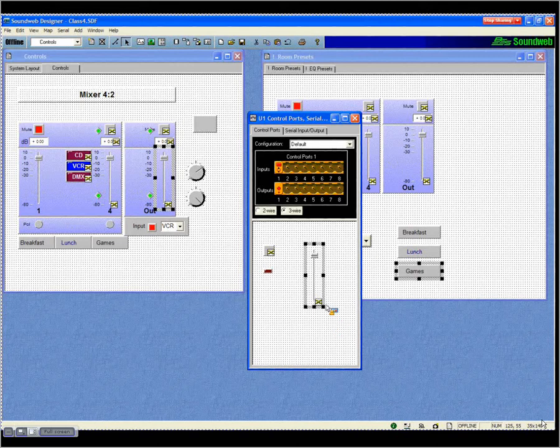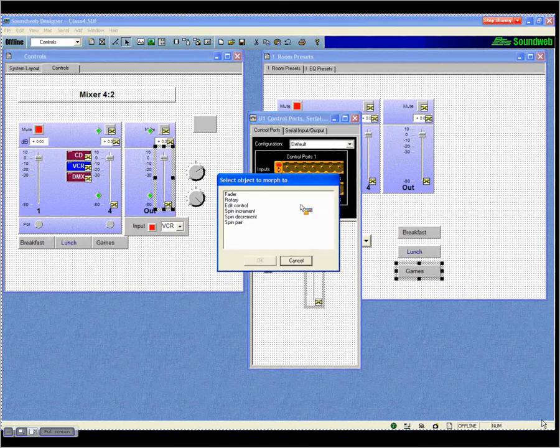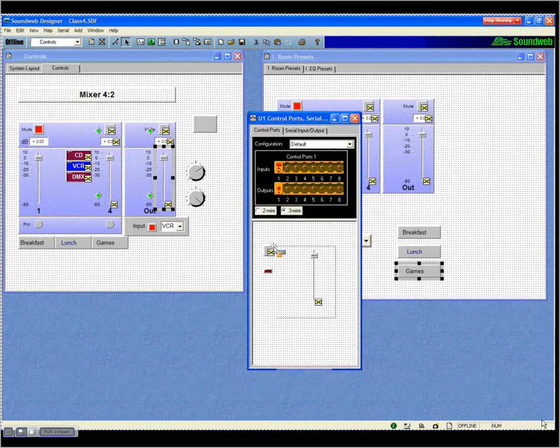Basically, the only things you can place on control outputs are things you can morph into an LED. So that's a good test for you. Just right-click on device, hit morph, see if it says LED in the list. Doesn't say LED, you're not going to be able to put it onto the control output. Not going to work. Again, the control outputs are just 0 to 5 volts. Very low current.